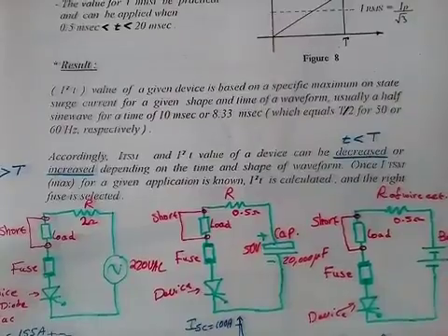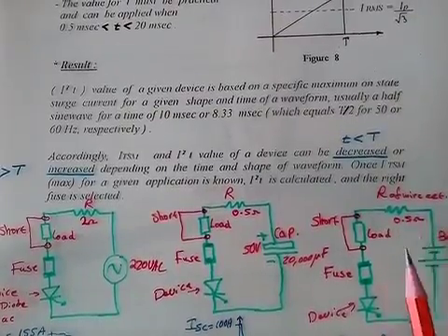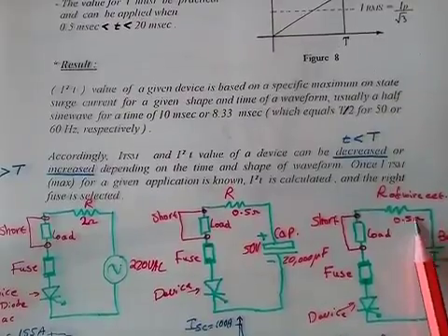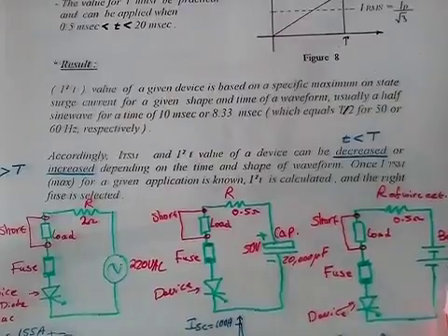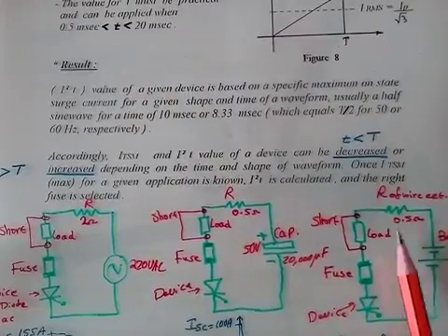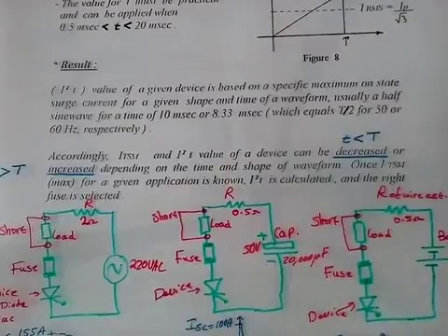And here the last one, suppose you have a load which is operated by a battery. In this case, it's a 24 volt battery, and the resistance of the wire, or resistance of the circuit, is considered to be 0.5 ohms. So dividing that 24 volts by the 0.5 ohm equals about 48 amps of a straight line DC current.